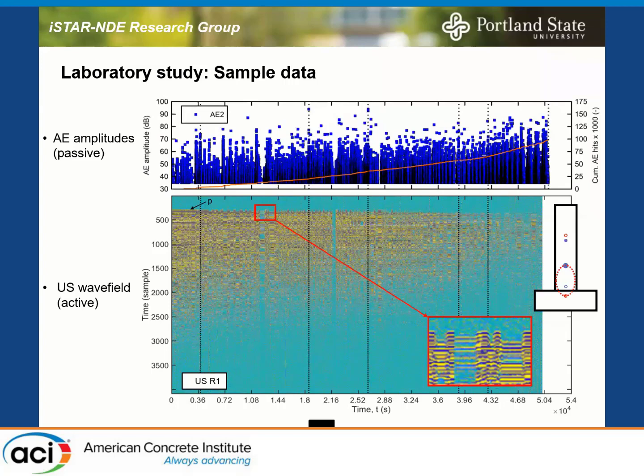If you wanted to image, you could do it, but you would have to have many more sensors, and you could do something like tomography almost. But the point here is to keep it simple and to hopefully get enough information to characterize the state of damage after an event. That's why we use as few sensors as possible. And you can space them out much more than we did. There are in-field tests where they have spaced them out 5 meters from each other.